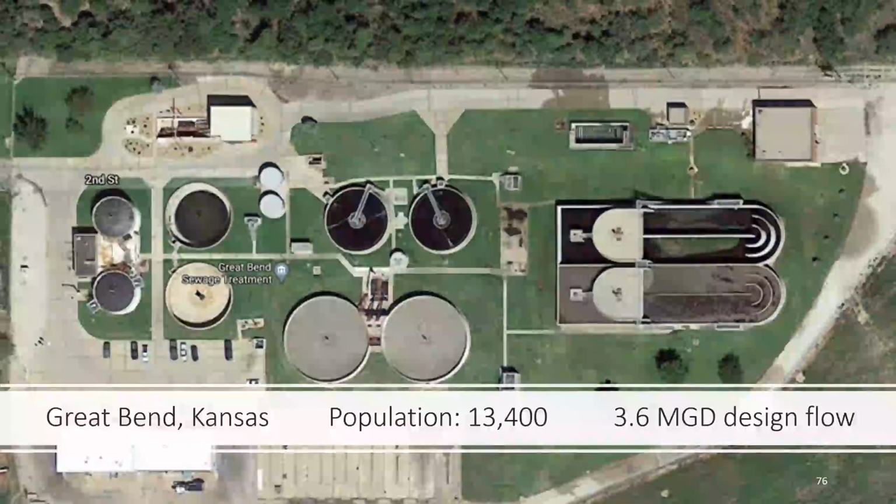Yeah, there you go. So you've got 3 days retention time. And with 3 days retention time, you have a lot of flexibility. You can probably go on and off for 2 or 3 times that many minutes. So make sure you're on long enough to get ammonia removal, and you can stretch your air off times in the winter. Okay, well, when you have those kind of results, you're killing it. And with 3 days retention time, it's understandable why.